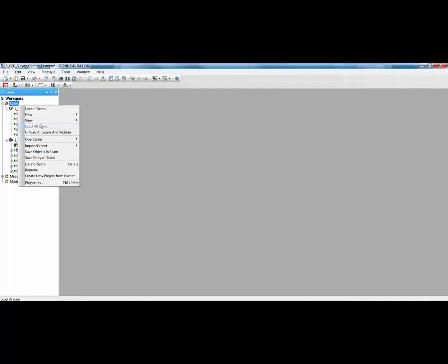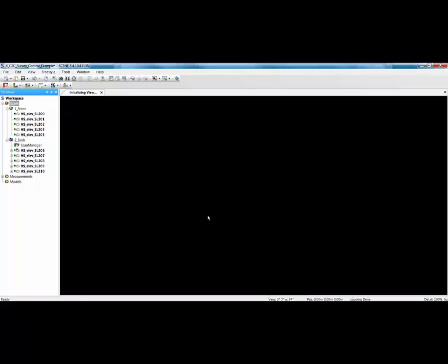Also, what I'm going to do is have a quick look at the correspondence view, and whilst we can see that I haven't got round to registering the front cluster yet, if I were to rotate this round at the side, you'll see that the transformation is wildly different between the two clusters. So the next process I need to go through is to register the front cluster, then register the master cluster up here to bring both of these clusters together based on this reference scan and this reference cluster.